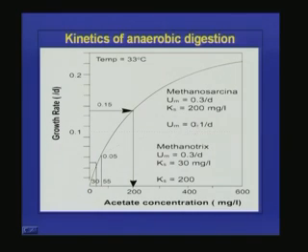So if you design a system with a BSRT less than 10 days, what will happen? Whatever time we are providing will not be enough for the regeneration of Methanothrix. So whatever is present in the reactor will wash away from the reactor if the BSRT is less than 10 days. That is the reason why we have to give a large hydraulic retention time as well as biological sludge retention time in anaerobic systems.